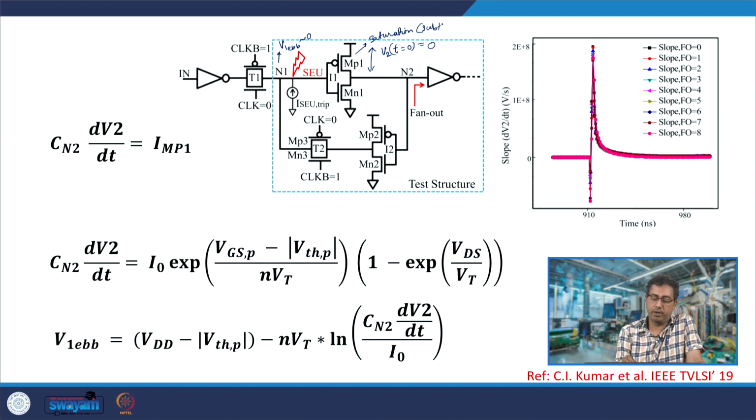Subthreshold saturation. Okay, so therefore you can neglect this term. Magnitude VDS is quite large for this, and in this you have included the DIBL. It is as if DIBL is for supply voltage, for VDS being near VDD. So with this we get the value of, what is the value of VGS here?